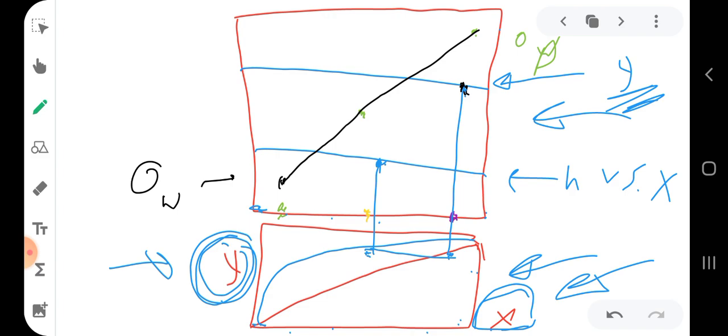So we start from here, we move downward until we reach the 45-degree line, then we move horizontal until we reach the equilibrium curve, then we move up until we reach the liquid enthalpy curve. Okay, so at the end of the day we reach this point.